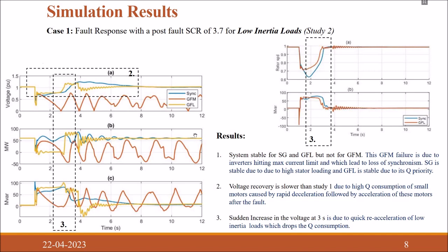Now if we compare the result, the voltage recovery condition, with the cases in the previous study, which is study 1, we see that the voltage recovery is low, and this is because of high consumption of small motors, because of which there is a rapid deceleration followed by acceleration during fault.